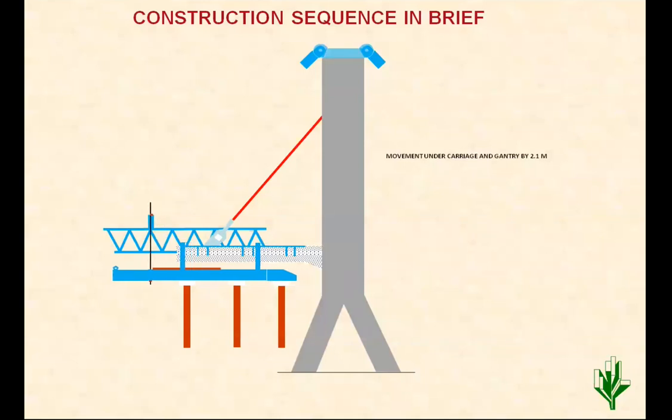So now the shuttering is at the next place, and it is not requiring any support from the ground, so it is free from any support below. Now that movement has also been done. Now the next segment of concreting can be done. So this exchange of support was required. Then the total staging below is cleared off, and the obstructed railway track has now been cleared. It is operating below this structure.